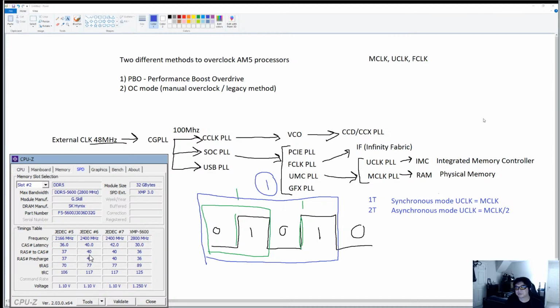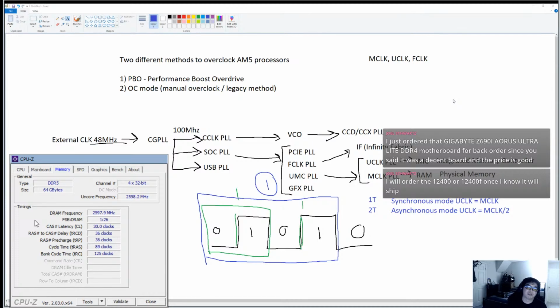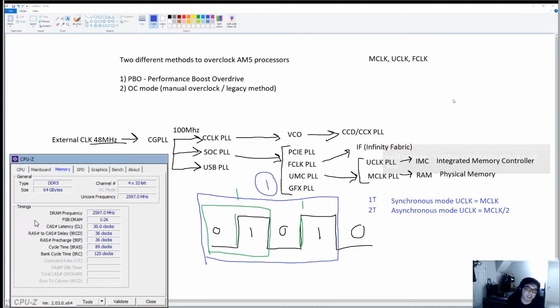But then after that, I bumped it up to 5200, since that was the official supported speed from AMD, and anything above 5200 on Zen 4 right now is considered an overclock, which is not supported. So it's kind of weird, because even though they say DDR5 6000 is a sweet spot, realistically 5200 is the stable 24/7, no headaches required type of setup.